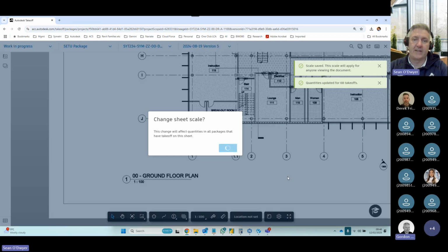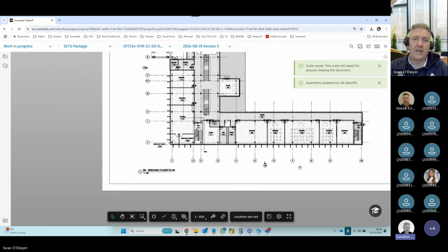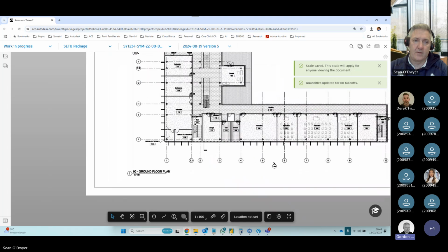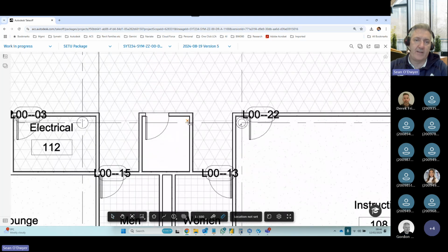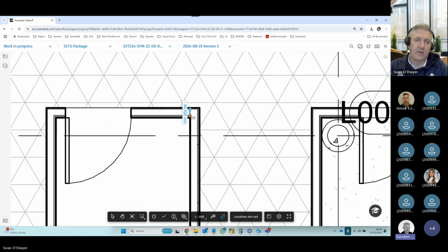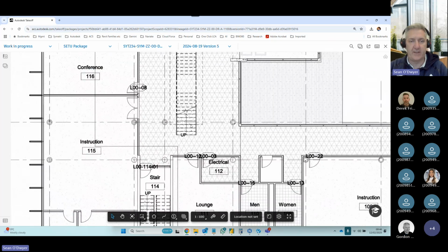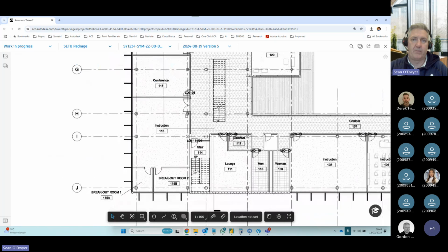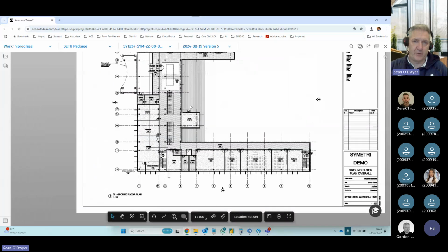Yeah. But then you're assuming that that's an A1 sheet at 1:100. But if it was printed as an A3 PDF from an A1, then it wouldn't be 1:100. You'd still have to calibrate it then. Yeah, and what you can do is a quick check by checking the width of a wall, just to see if it's within range, like that's roughly a 90mm stud, which is okay. Or you can check the width of a stairs, something that you know is a constant. But preferably, we always say to customers to have at least one dimension on the drawing if you're doing takeoff.